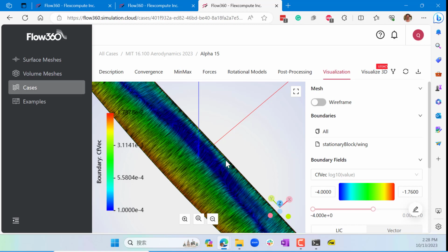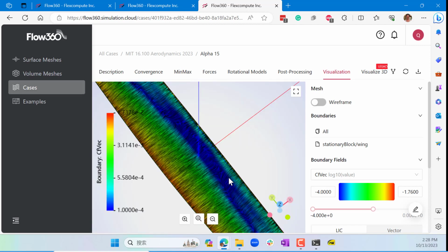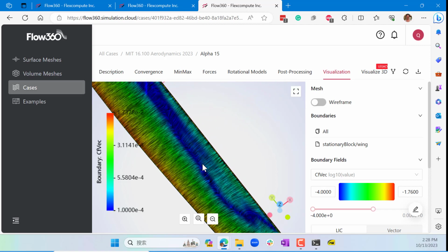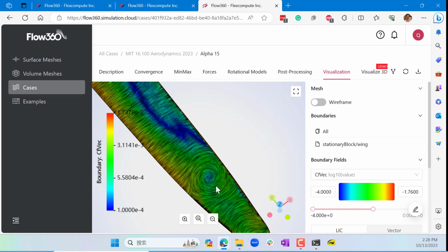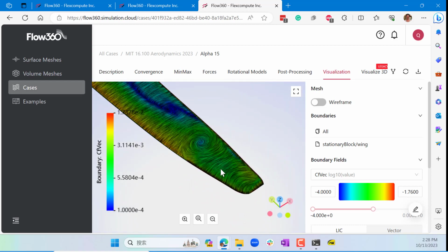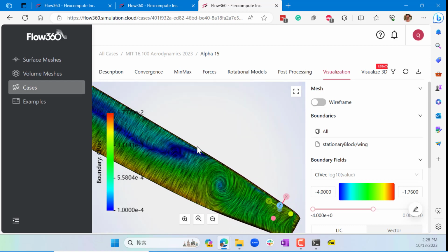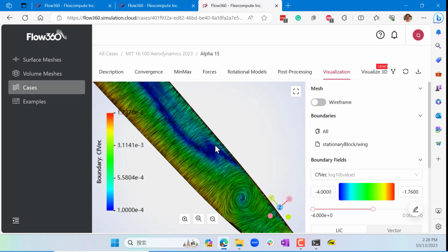And afterwards, there is a shear stress, but it might be because of the reverse flow in the separated region. And then if you go towards the tip, you see a huge vortex sitting over here, and it turns out that the entire tip is massively separated. So we're going to see a little bit in the volumetric flow later how it is going.